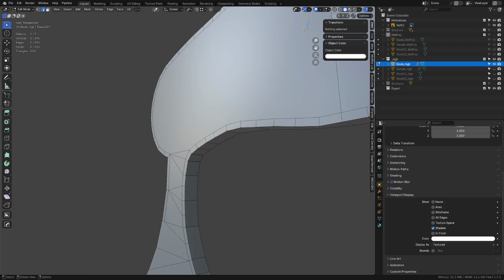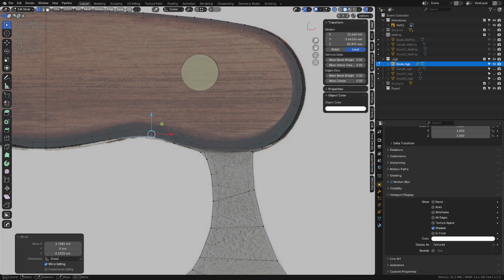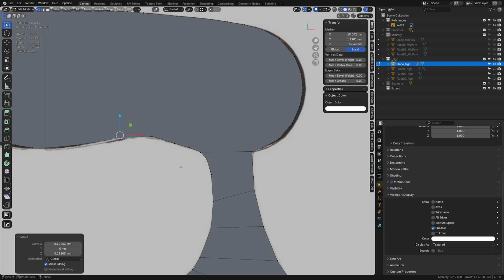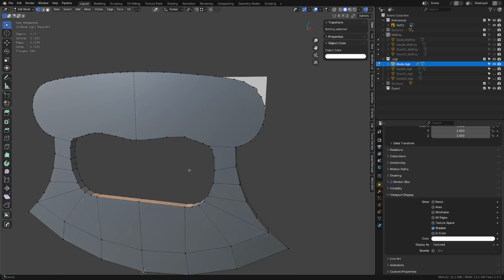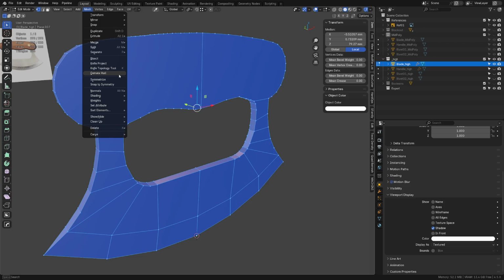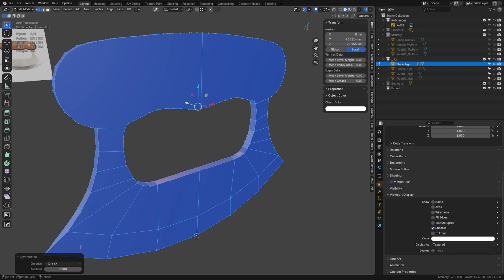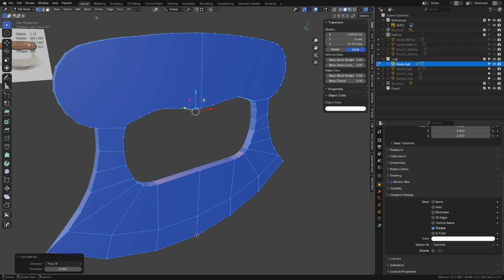I'm going to dissolve that edge for just a second, so I can move these around and balance them a little better. Okay, it's getting a little bit squirrely because our back faces are all the old topo. All right, so let's symmetrize it real quick. We're just going to select it all, Mesh, Symmetrize. The arrows point in the positive direction, so in our case, it's negative Y to positive Y to go across in that direction. And then we do it again. You should be able to just hit Shift R, I think. No, maybe not.